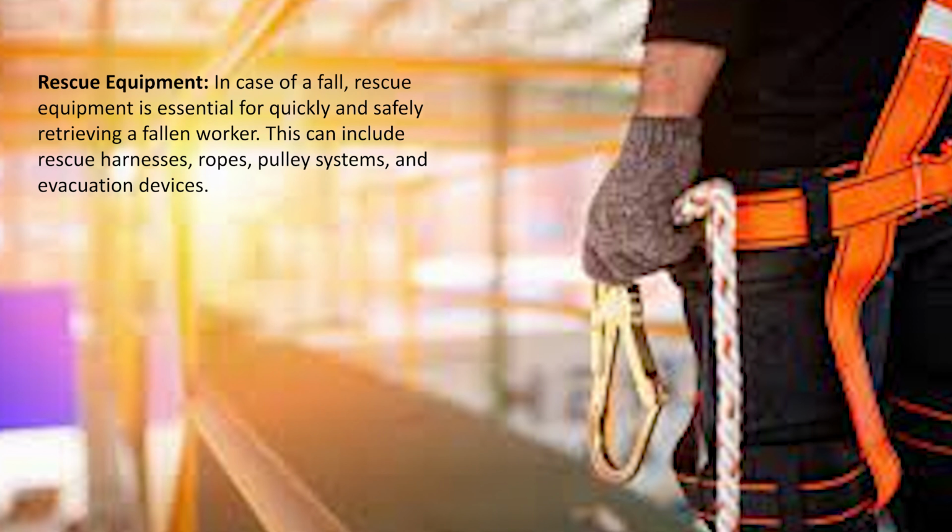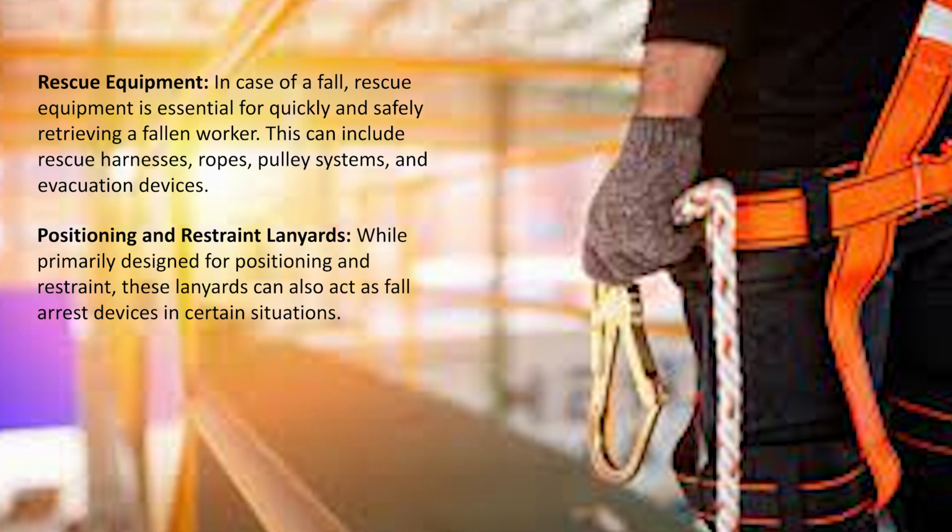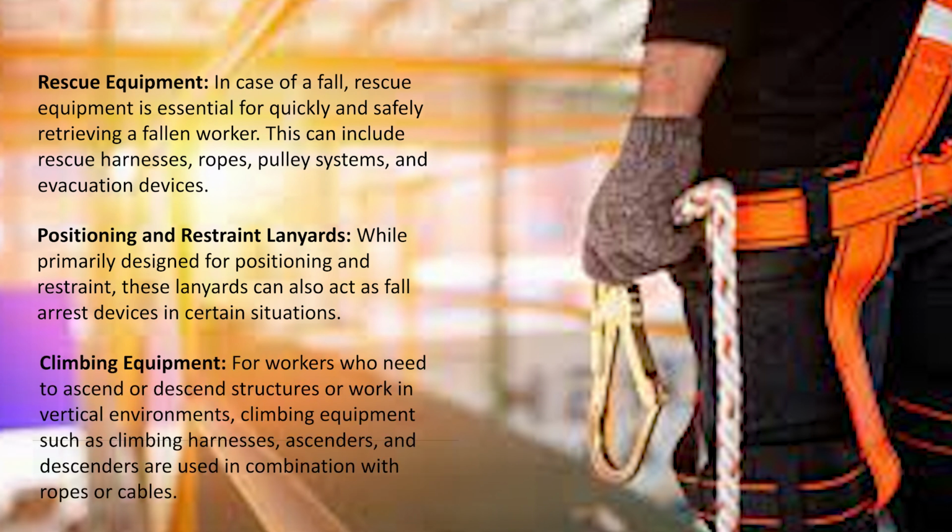Rescue equipments. In case of a fall, rescue equipment is essential for quickly and safely retrieving a fallen worker. This can include rescue harness, rope, pulley system and evacuation device. Positioning and restraint lanyard. While primarily designed for positioning and restraint, these lanyards can also act as fall arrest devices in certain situations. Climbing equipment. For workers who need to ascend or descend a structure or work in vertical environments, climbing equipment such as climbing harness, descenders and ascenders are used in combination with rope and or cables.